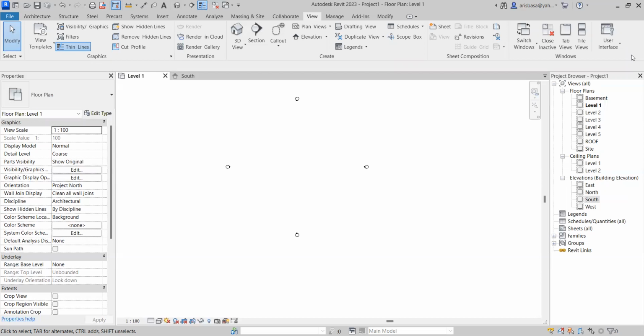So since we are doing a 6-story building, let's use a grid of 4 meters. Okay, a 4-meter grid from column to column. So maybe we can have 4 grids. So we'll have a building of 16 meters by 20 meters. Okay, 20 meters deep. I will sketch it here. 4 by 5 grids. So if you are fast, you can do this faster than me. So this will be our grid.